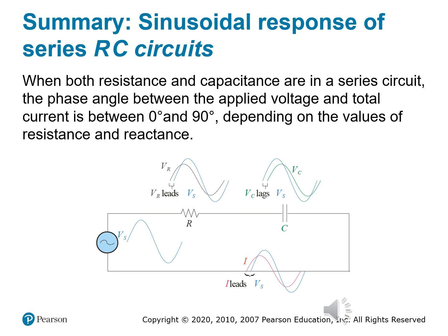So let me go ahead and paint this picture for you. The resistor voltage V sub R, or VR, is in phase with the current, and the capacitor voltage V sub C, or VC, is behind the current. The total voltage Vs, the source voltage, is the vector sum of both. It's a subtle tug of war between the resistive and the capacitive sides of the force. May the force be with you. Yes, I had to say it.